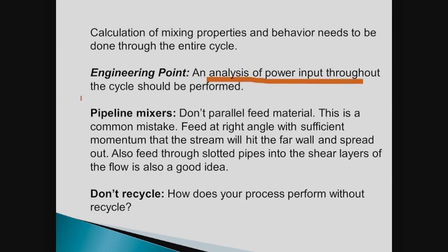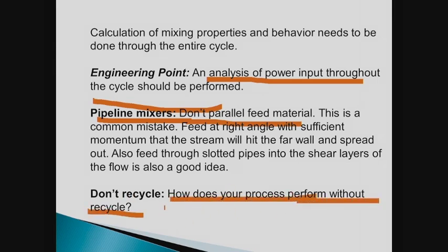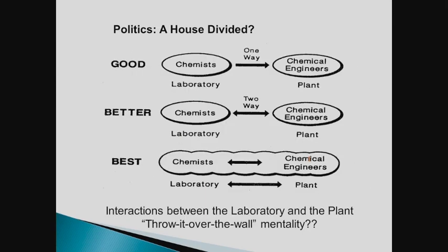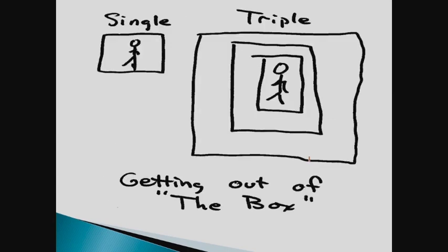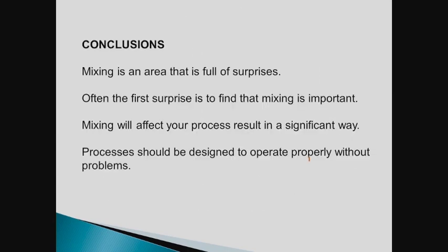Analyze power input throughout the cycle. Don't parallel feed in a static pipeline. Don't recycle. Does your process perform well without recycle? Feed at a right angle with sufficient momentum for the stream to reach the far wall. Let me talk about some of those. Let's talk about